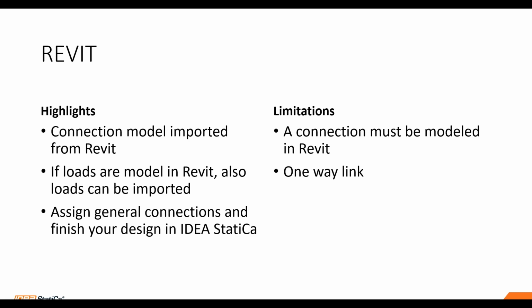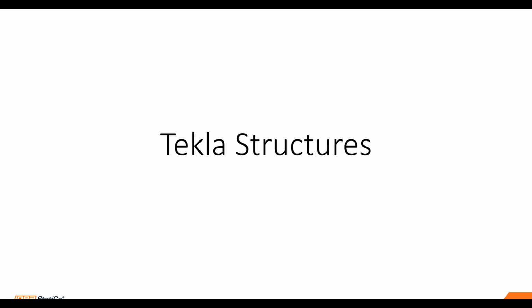You can assign general connections and finish your design in IDEA StatiCa, as the second example I showed you in the video. And well, the limitation is that a connection must be modeled in Revit. Okay, that's, let's say, a kind of limitation because we are transferring the model of the connection. And it is a one-way link. We cannot transfer information back to Revit. Okay.